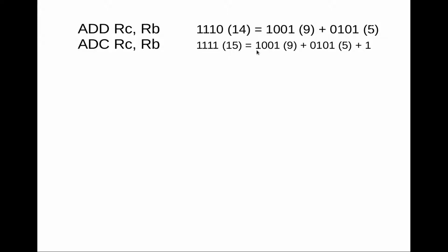Another instruction we're interested in is an add with carry instruction. So, in this case, we're dealing with 4-bit arithmetic. So supposing we wanted to add 2 8-bit numbers, we'd have to do it in 2 steps. And so we'd use the normal add instruction for the lower 4 bits of our value. And if that resulted in a carry, so if the result of that was larger than 15, then when it came to adding the higher order bits, we'd like it to add that carry as well as the 2 higher order portions of the numbers we're trying to add. So in effect, that's an addition with an extra 1. So we want to have an instruction to do that as well, so we can easily implement higher bit count arithmetic.